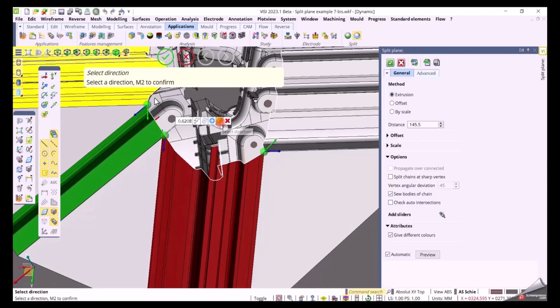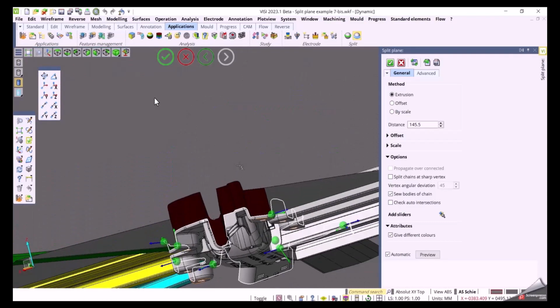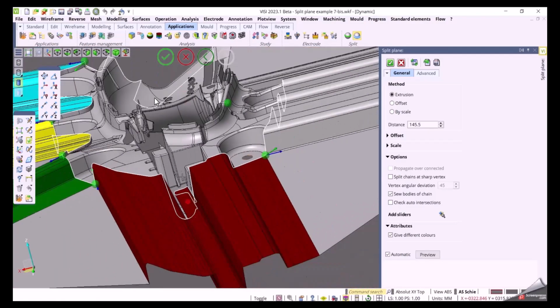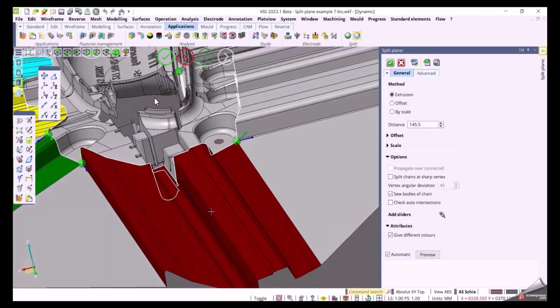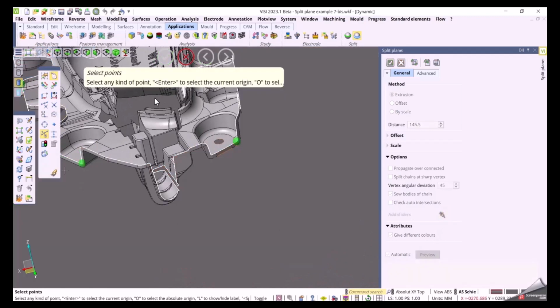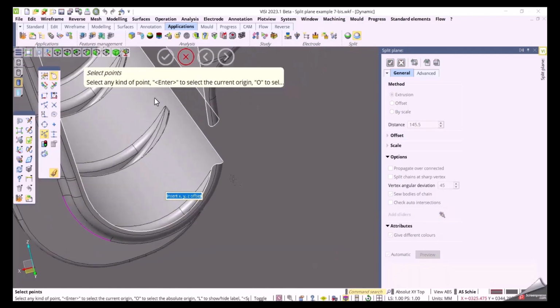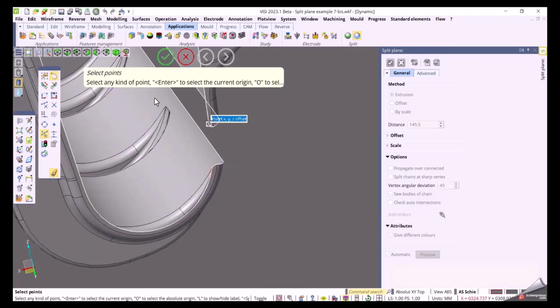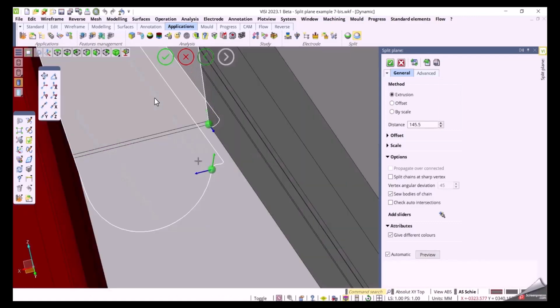So we can actually go into here. You can see how that split plane actually goes into the part. We're changing the direction around as well, and it creates a clean opening. Now, let's say where that is actually going into the part, we can add an additional slider. Pick between 2 points. And then go ahead and rebuild it.